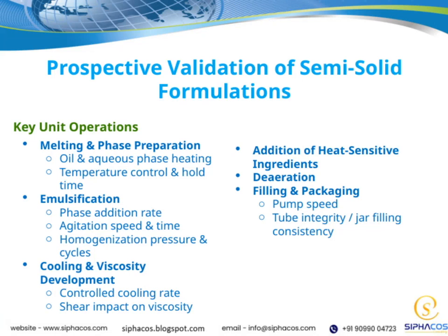Now, let's dive into some of the key steps involved in developing and validating our semi-solid formulations. First, when adding heat-sensitive ingredients, we need to be very careful to preserve their stability and activity. Deaeration is also critical here. Removing air helps prevent oxidation and ensures product quality. Next, during filling and packaging, controlling pump speed is essential to maintain accuracy and consistency, while ensuring tube integrity or jar filling consistency helps us avoid leaks or uneven filling.